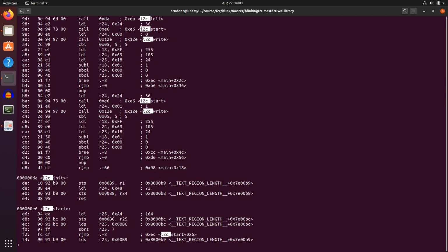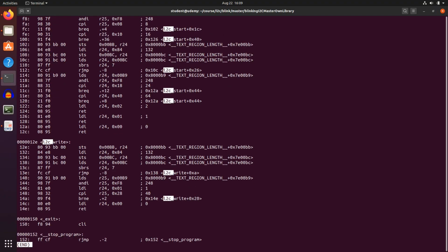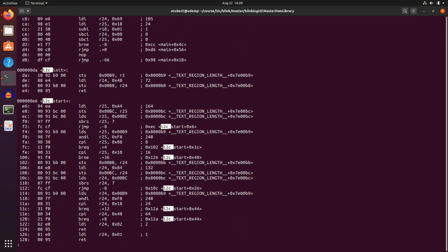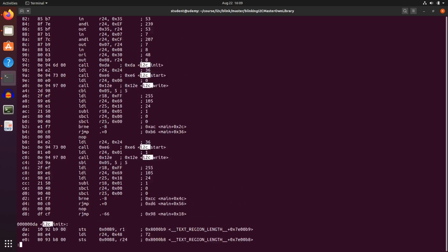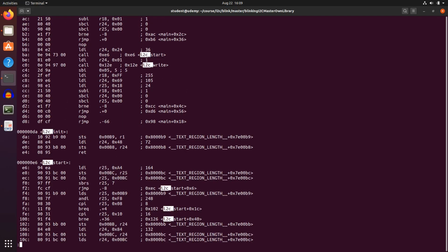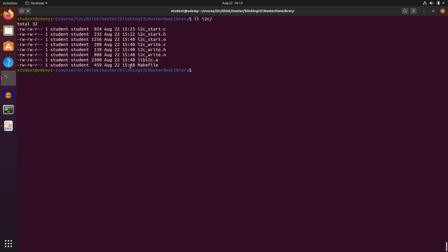I2C. So I have I2C init, I2C start, I2C write, and there is no stop any longer. So the linker recognizes it and removes I2C stop from the integration into my executable. However, this library might also be used by others who compile their executable source code a little bit differently. So let me show.